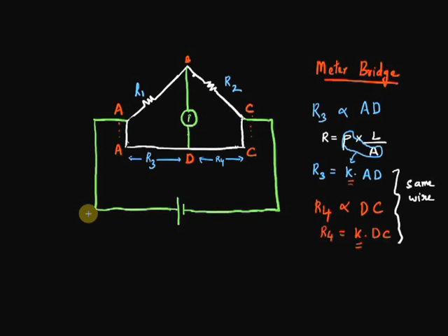So what we do in our meter bridge is to keep adjusting the position D of the galvanometer along the wire AC until there's no current flow through BD. When no current flows through BD, the potential difference between B and D will be zero, just as we discussed earlier in the Wheatstone's bridge. So similar to the case before, voltage along AB will be equal to the voltage along AD.